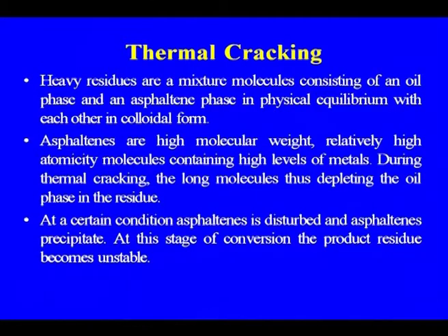During thermal cracking, the long molecules are cracked, thus depleting the oil phase in the residue. At a certain condition, the asphaltenes are destabilized and the asphaltenes precipitate. At this stage of conversion, the product residue becomes unstable.